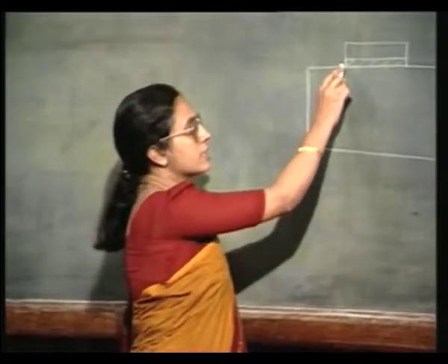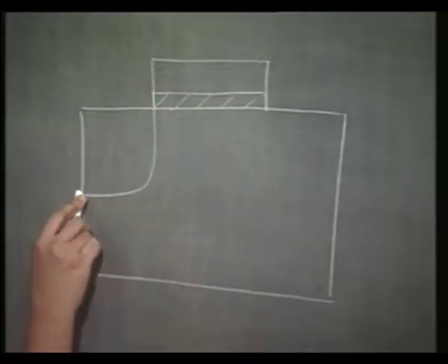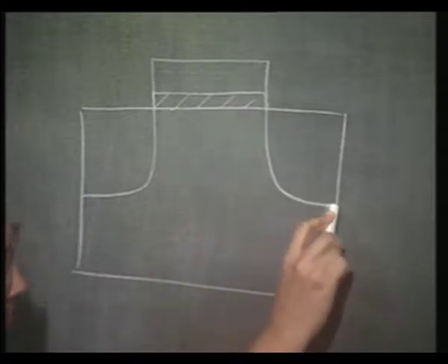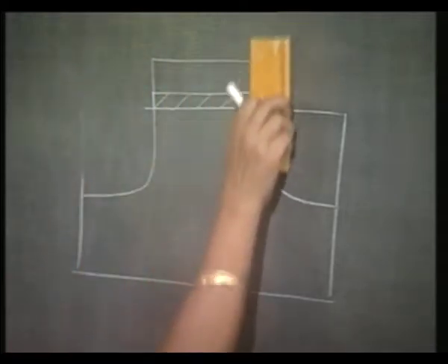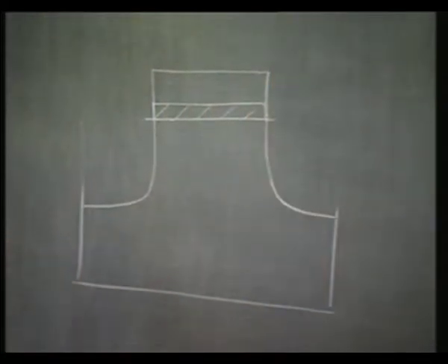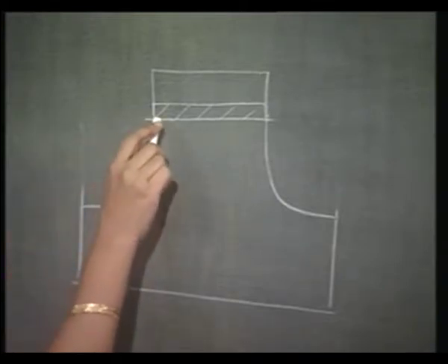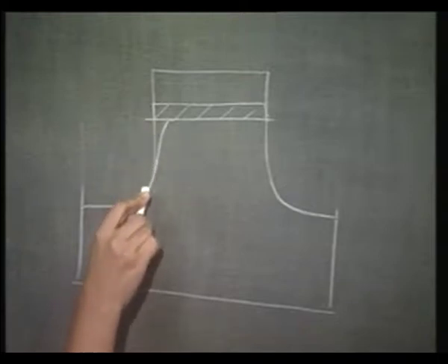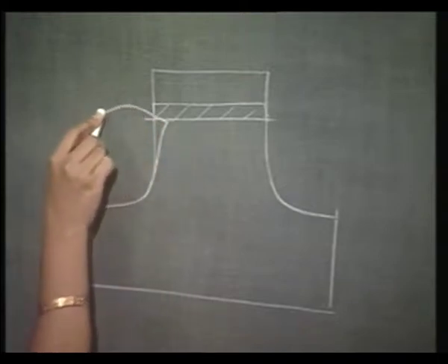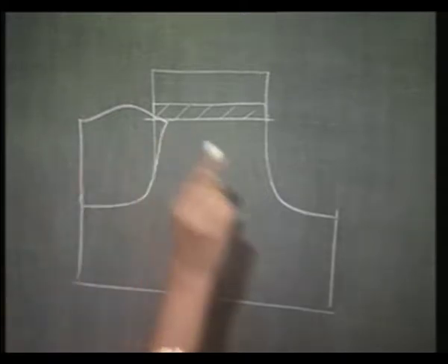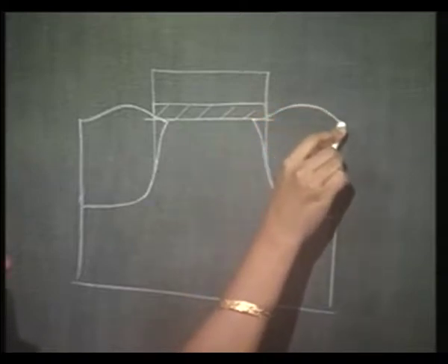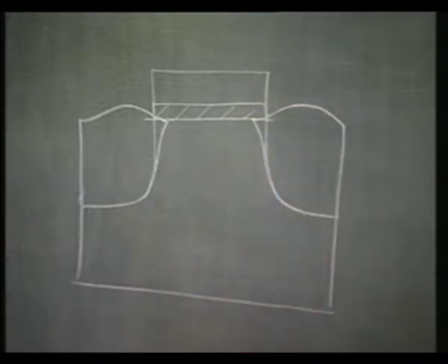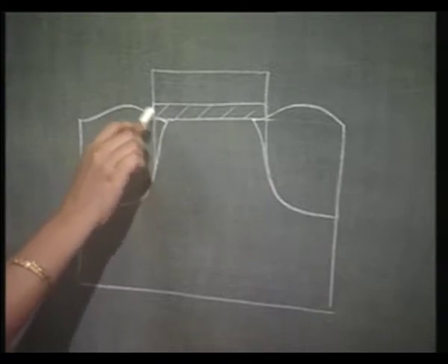Okay. So, now let us say I want to etch these portions, and then I want to grow the oxide. That is the recessed local oxide isolation. So, when I am doing that, you see there will be a little bit of encroachment of oxide underneath this silicon nitride.